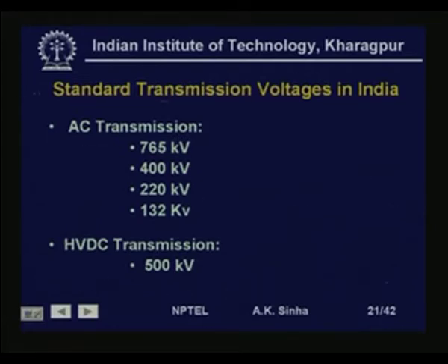Where we have a small transmission line, we have worked at somewhat lower voltages also. That is, when we connect two systems which are very near to each other, and the transmission line is very small, we call these systems back to back HVDC systems, and here we have worked at lower voltages as well.